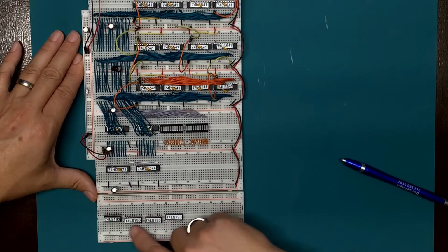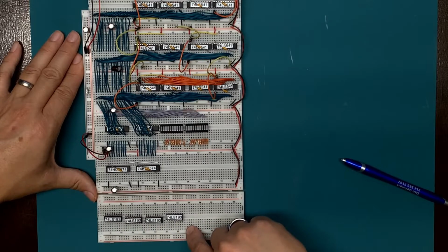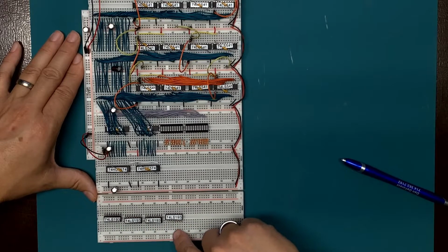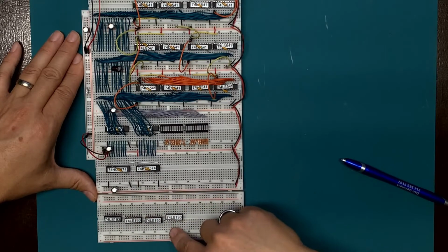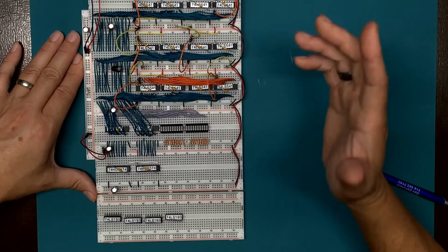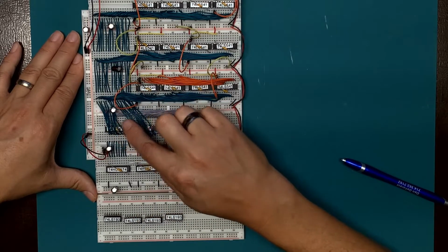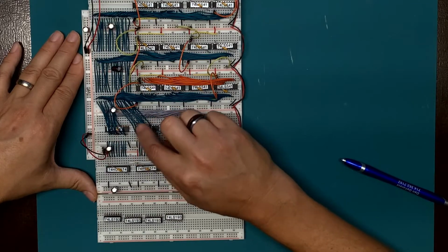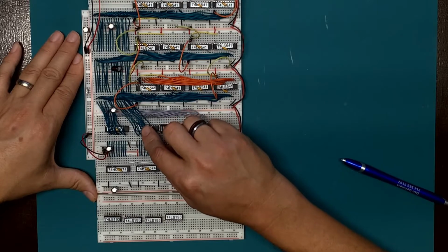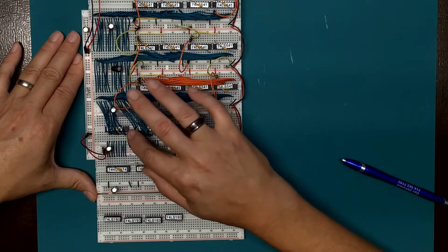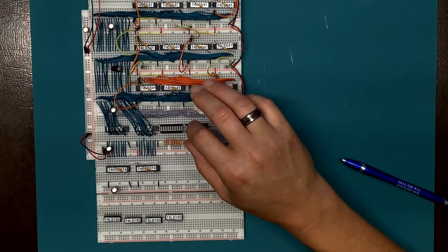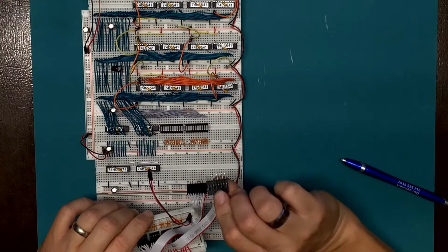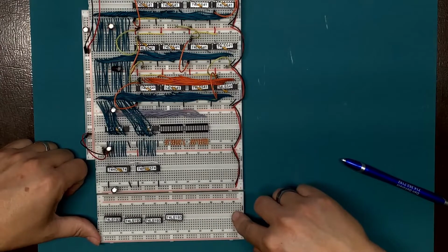I don't like the pinning of these. It's really messed up all over the place here. And so I will end up trying to pull wires over the integrated circuits. Ideally, if I had the room, and I don't believe I do, I would arrange it like I did here, where I pulled the wires out to a common spot, which then I could just tie the ribbon cable lines in directly. And I don't believe I'm going to have that kind of room on this board.